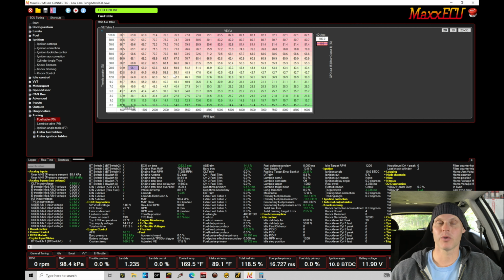The very first thing I want to do is prep all of my tables so that when we move into our high cam, we're going to have reasonable starting values for fuel and spark timing, and making sure everything is going to be in order there. So let's go and take a look at how we set up our calibration file. A little bit unique, this is the way that Honda goes in and calibrates working with VTEC functionality on their engines in the factory ECUs. So let's look at this real quick.